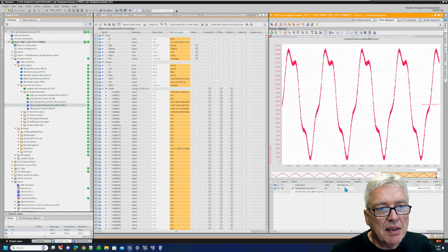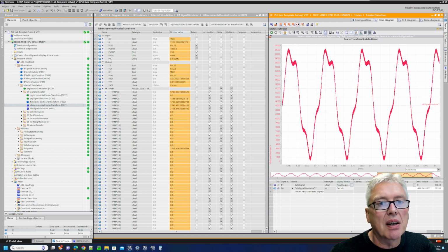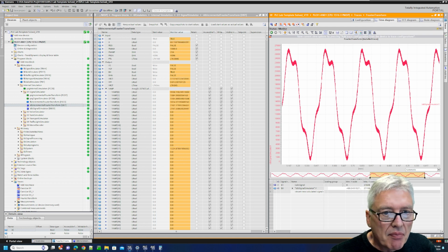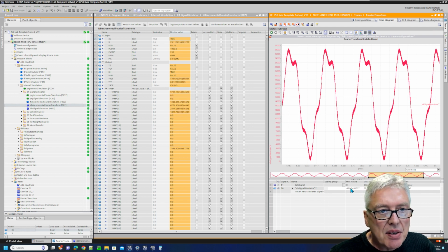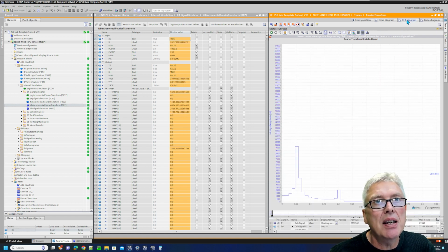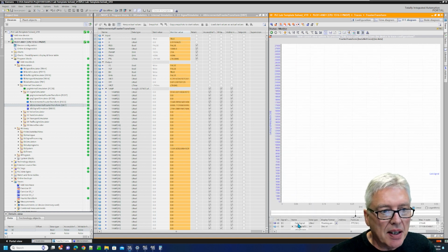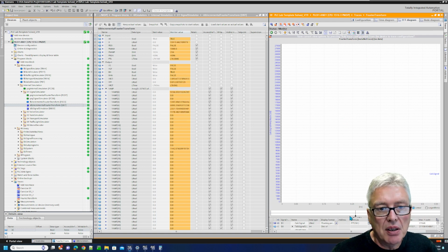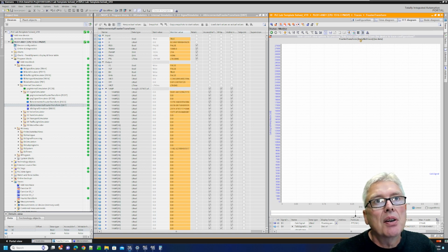When you have added that, you can insert a new calculated signal, and then you can activate this function. You probably can't do it while it's running online. And you say you want an FFT analysis of the signal here. That's the noise signal you see, and in the FFT, you select that. It doesn't show anything here, because you have to stop the recording to have it analyze. No data.